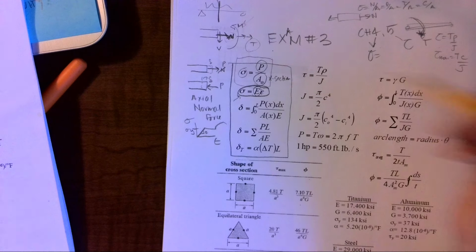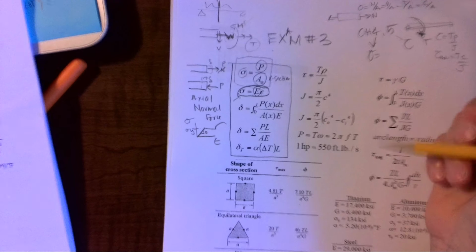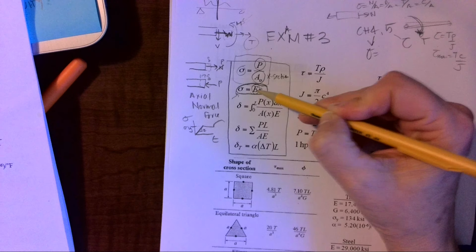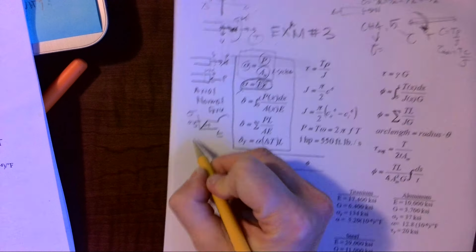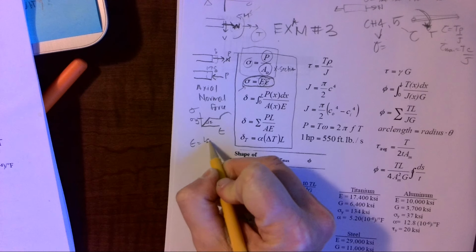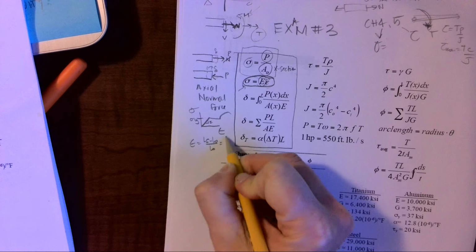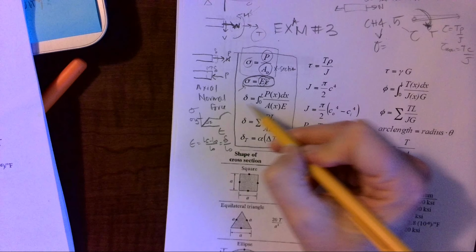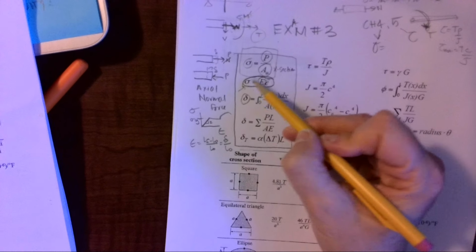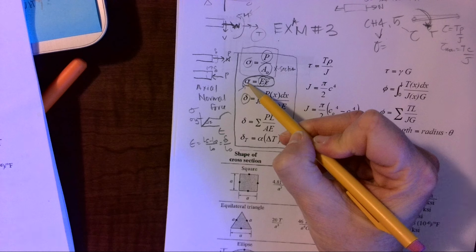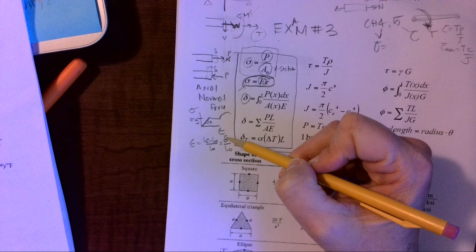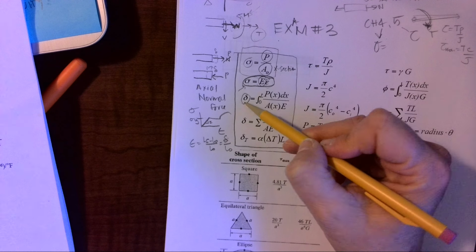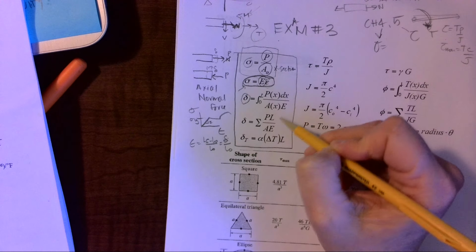So our assumption with all of these equations is that we are in the elastic region. So material behavior, modulus of elasticity, results in strain. Strain is length final minus length initial over length initial, which is our delta over length initial. That's where this equation comes from. It is taking P over A, which is my normal stress, and it's taking my modulus of elasticity, and my strain is change in length over length. We can rewrite that: delta equals PL over AE.